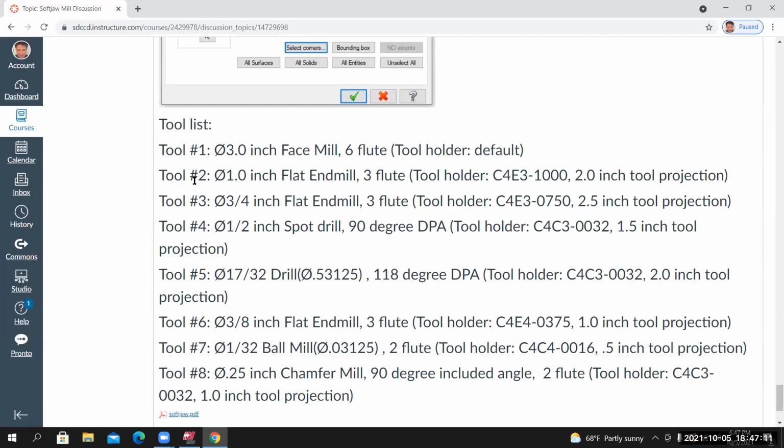So the roughing tool is going to remove the material quickly, but it's not going to leave a great finish. But then we're going to come in with a dedicated finishing tool, and it's going to leave a much nicer finish. It's going to do a lot less work, and we can dedicate a brand new tool to the finishing process, where we could have a slightly used tool dedicated to the roughing process, where we might even have a roughing tool that uses indexable inserts, and it's just not capable of leaving a great finish. So different methods. A lot of times when I'm cutting, especially when I'm cutting things other than aluminum, I'll have a dedicated roughing tool and a dedicated finishing tool.